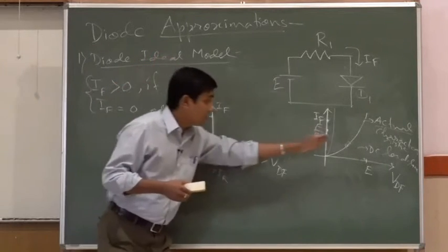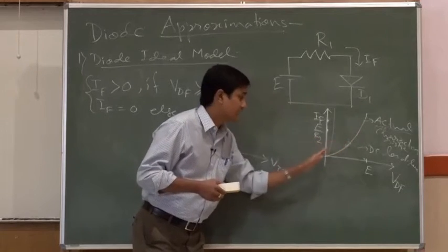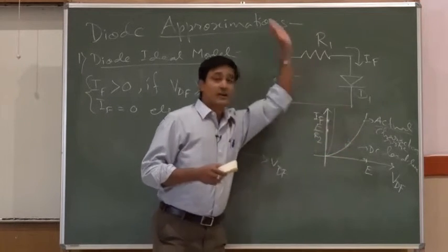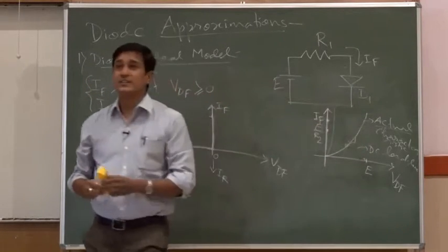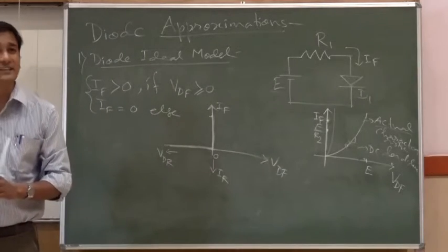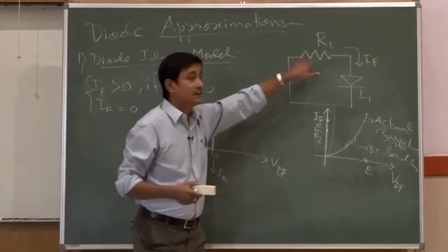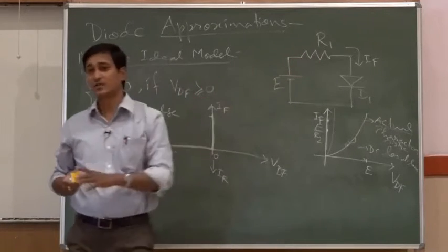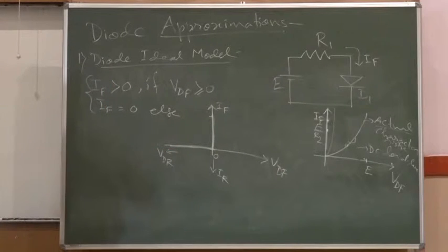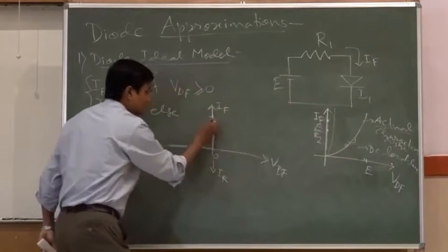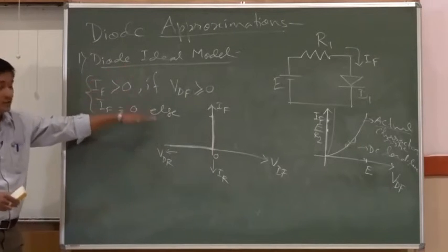So, it is purely an approximation of this curvature, where we are considering that with a small increment of this voltage, current will go very high, and with a small variation of this voltage, the current changes very much. So, the diode has nothing to do other than the electrical circuit element which is connected to that circuitry. That is why we say that in this condition, if the diode voltage goes beyond 0, things will be purely controlled by the external electrical circuit element other than the diode. Okay. So, that way we convert this actual characteristic into this form, where our model goes this way.